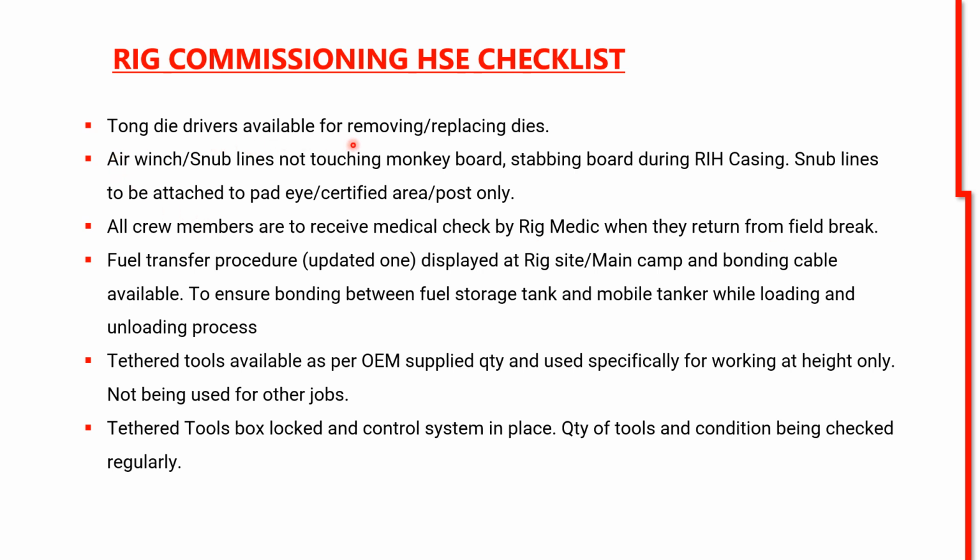Strong drivers available for removing and replacing dies. Air winch, snub lines not touching monkey board, stabbing board during RIH. It means running in hole casing. Snub lines to be attached to certified pad-eye points only.